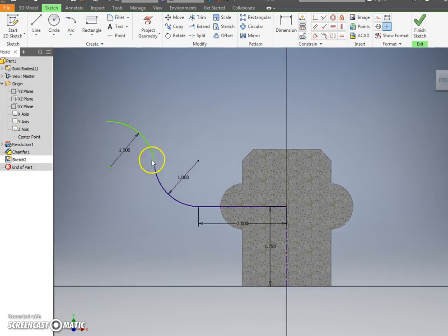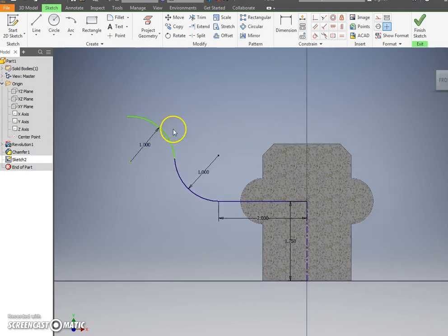Okay? The final step to get the geometry made, we're still going to work on resizing this some, is a line. And I'm just going to dump a line out here. Now, when you do this, this needs to be a tangent line. Mine may be, it may not, yours may be not, I don't know. So click tangent, click this line and this arc, and this will lock this to this so it always stays tangent. So you shouldn't have to worry about that a whole lot.